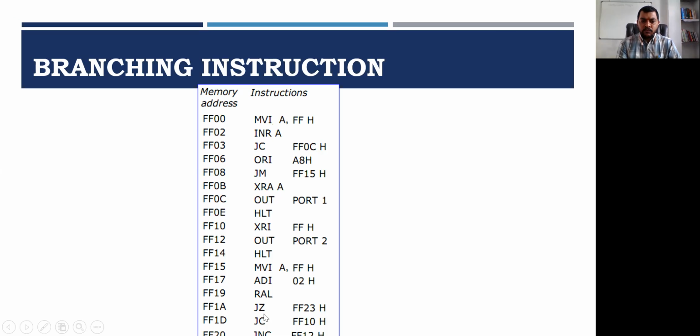If you are able to see FF1A, JZ, right? Jump if 0 and JC. So at this point, it is going to jump at this location FF23. So FF23, it's after this. So FF10, it is backwards. So here it is FF10, right? So this is back. So you have to write like that, a label where we are supposed to jump. So in a program, there are many jumps. I just need to show you this program. I don't know what this program does, right? So just to tell you how the jump instruction or the branching instruction works, to jump or to change the sequence of the program, right? So we'll start with those instructions.